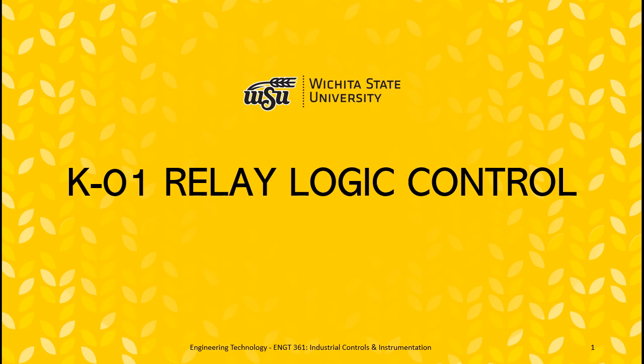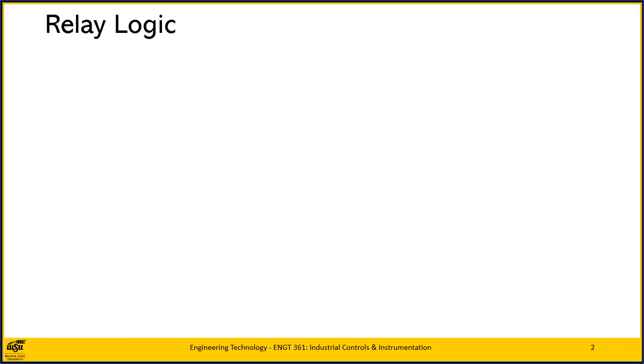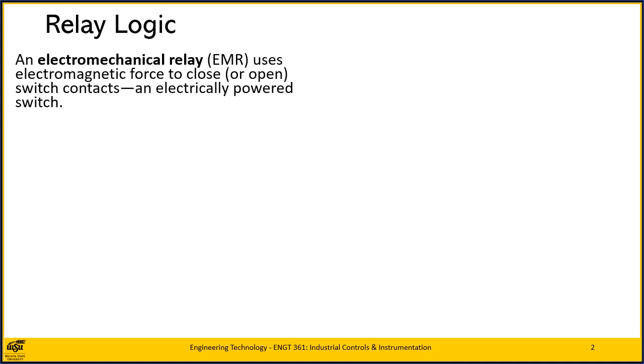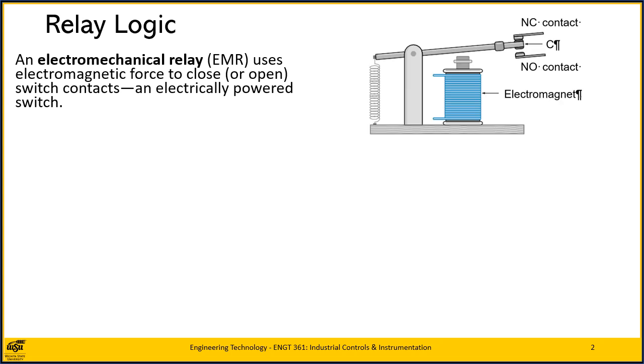K01 Relay Logic Control. Relays as devices are covered in Module D. However, a quick review of the basics is appropriate here. An electromechanical relay, or EMR, is a device that uses electromagnetic forces to close or open switch contacts. In other words, an electrically powered switch.